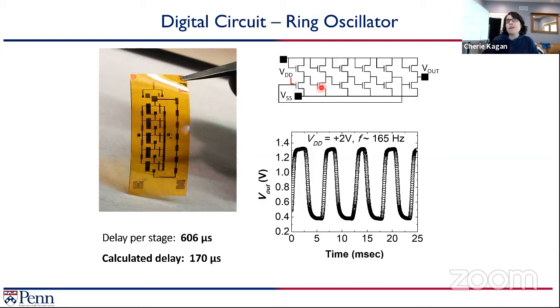That high voltage out will now become the input of the next one. So you should expect a low voltage back out of the next one. So watch what happens. If I have a low voltage in, you get high, low. So that low voltage in drives this one to be high, which is now the input of the next, which brings a low voltage out, which makes the next one high, the next one low, the next one high. Now that high can then be read out here by this circuit, or what happens is that these are also tied together, and that high comes around this wiring and becomes the input now of the next cycle of this ring oscillator. So now if it becomes high, then its next one is going to switch and this next one is going to become low.